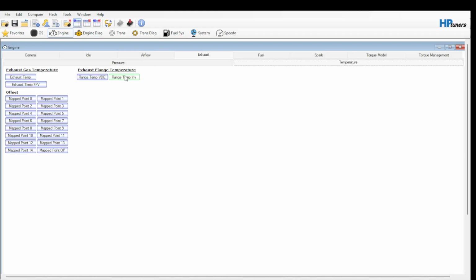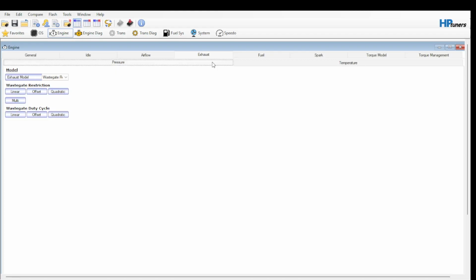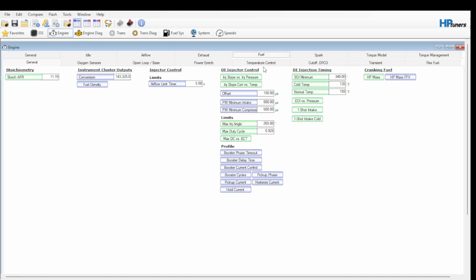But yes, this is the other thing I see people do a lot, is they just completely outscale this. I wouldn't outscale this personally. I've changed the values at above 4,000 RPM because, well, if I'm above 4,000 RPM and I'm flooring it, it's probably because I want to go somewhere without really caring much about the manifolds.